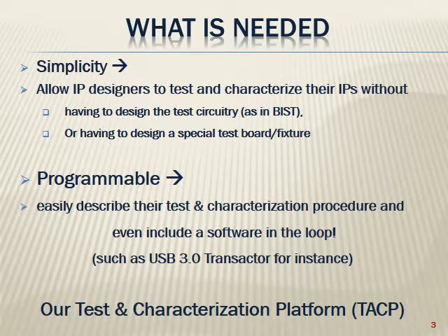So what is really needed by IP designers is, first of all, simplicity. We want to allow IP designers to test and characterize their IPs without actually having to design any special type of test circuitry as in BIST, or having to design a special test board and fixture. Also, the platform must be programmable so that they can easily describe their test and characterization procedures and maybe even include some kind of a software in the loop. This is where our test and characterization platform, TASIB, comes into play.